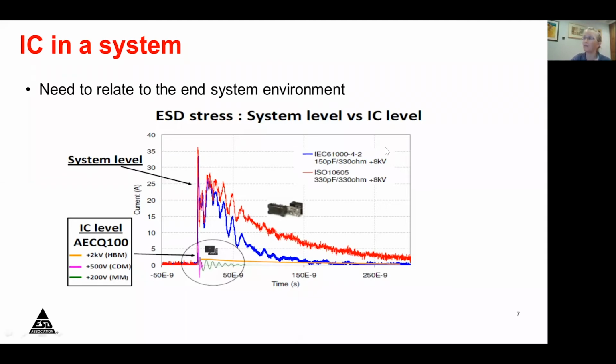This 8,000 volts is a model that represents that type of discharge, given different types of Rs and Cs. It also corresponds to a peak current of perhaps 30 to 40 amps at this first peak. This is just to give you some context as to real world static that you can feel every day, and this relates to how we're going to protect the electronic components.